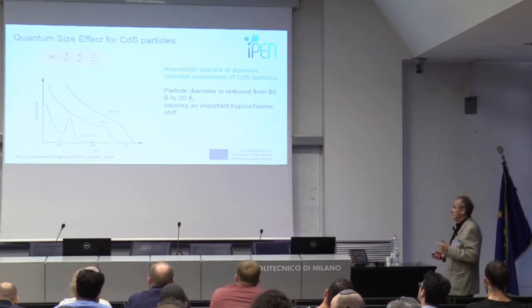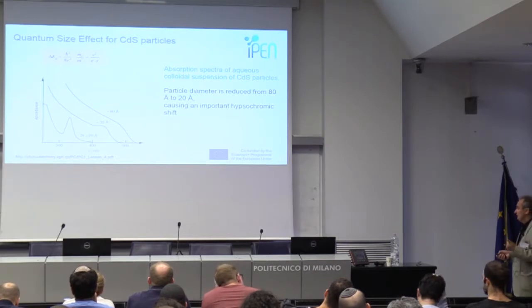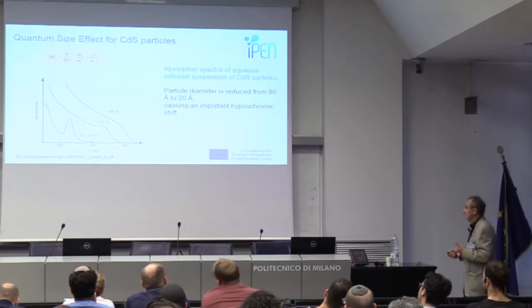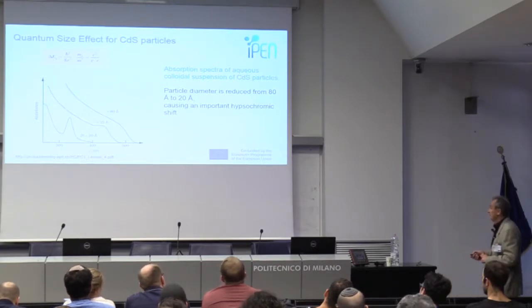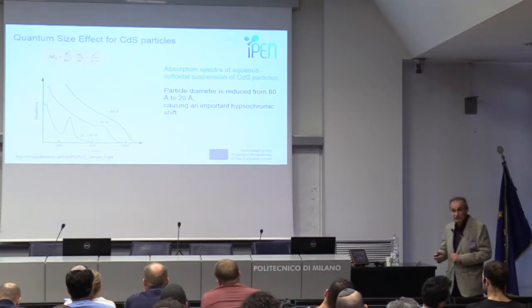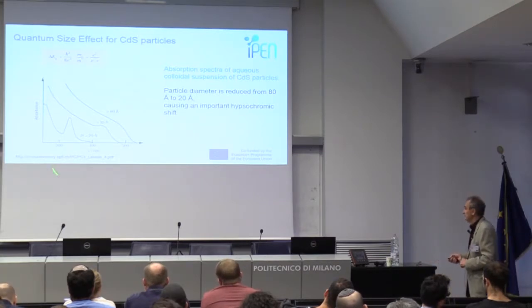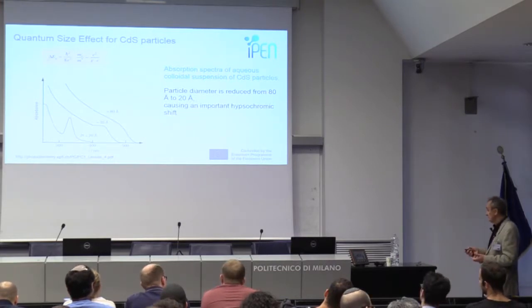And if you try to make production with a laser on some semiconductor, you should remember that if you have a volume material, nearly 80 angstrom, yeah, it's volume material, or you have 20 angstrom, the shift is really huge. And if you think about a laser with which you would like to do manufacturing, it's of critical importance.